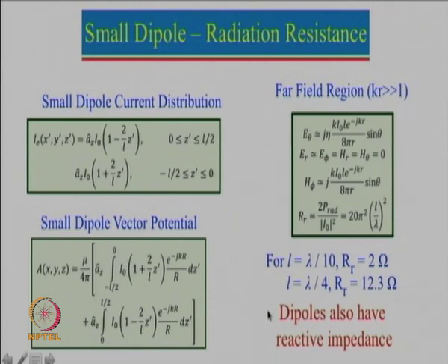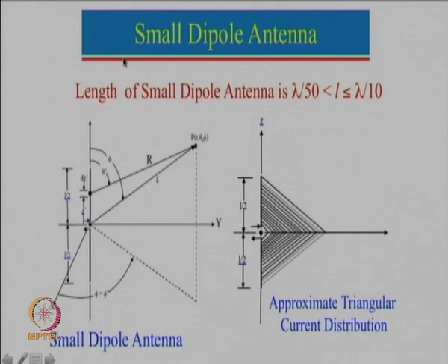For that, we will think again about a dipole antenna, and just look at this here. There are 2 arms, one arm going up, one arm going down here, and this has to be fed with current from here. So, what we really need is a current going in here, which will be, let us say, in this direction, and then the current will be going like this, and it has a reverse current here which is going in this.